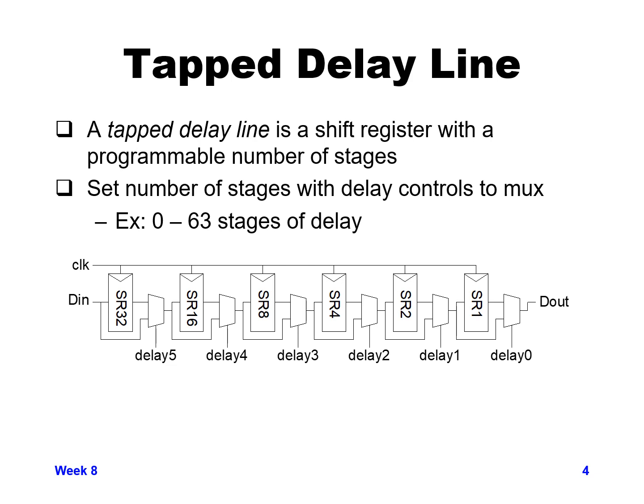And the way that this is done is we have a set of shift registers that are between 1 register up to 32 registers by factors of 2. So we have a shift register that's 1 long, a shift register that's 2 long, 4 long, 8 long, 16 long, and 32 long. Then we use muxes in between the shift registers to decide, do we allow the data to bypass a given shift register, or does it need to go all the way through that shift register?